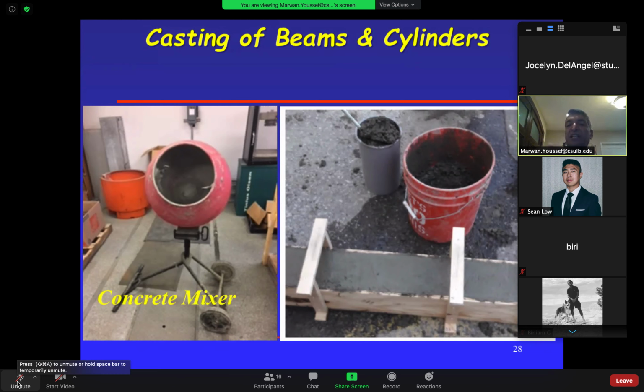Why? Because in that time, the process of hydration is taking place, and you don't want that to happen too much, because really the concrete is getting cured in the truck before it gets to the forms, and we don't want that. So you have to be careful. Sometimes a driver messes up and gets stuck in traffic, comes late, and in order to fix it, he starts spraying water and mixing it again. It makes the concrete bad.